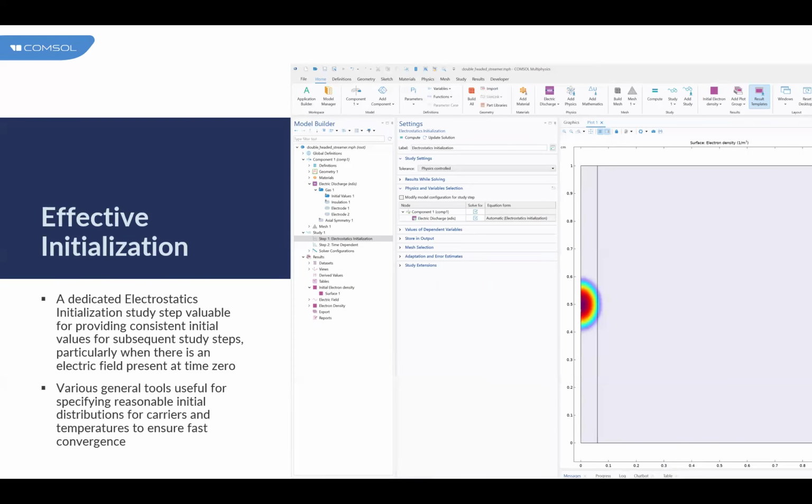The initial condition for the carrier number density cannot be zero and is set to a finite small value by default. They had better represent some initial electron seed in a zone of interest to ensure fast convergence. Same is true for magnetohydrodynamic simulations, providing initial non-trivial temperature and conductivity distributions.